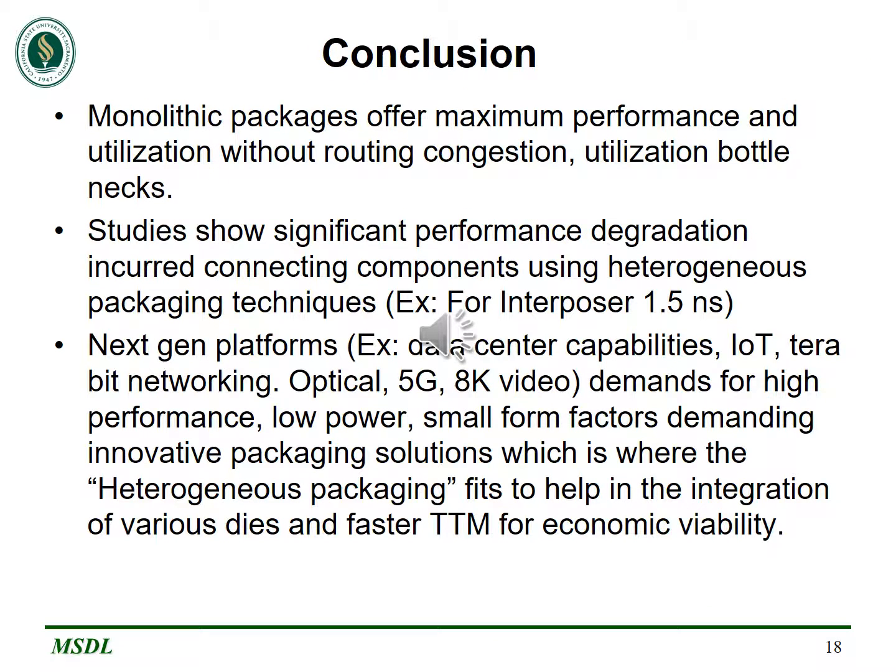Let's conclude this. Monolithic packages offer maximum performance and utilization without routing congestion and utilization bottlenecks. Studies show significant performance degradation is incurred connecting components using heterogeneous packaging techniques. For example, if we consider the interposer, it's 1.5 nanoseconds.